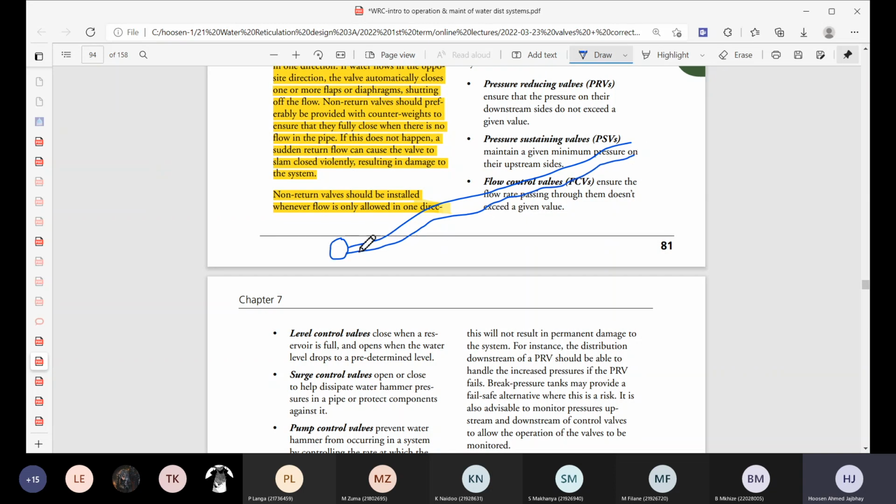While the pump is operating, the water is flowing upwards. But if the pump were to switch off, like load shedding, or normally because you've pumped enough for the day, then you have this column of water that's sitting there and you can get backflow occurring to the pump. It'll then backflow through the pump and may empty out into your pump station or whatever.